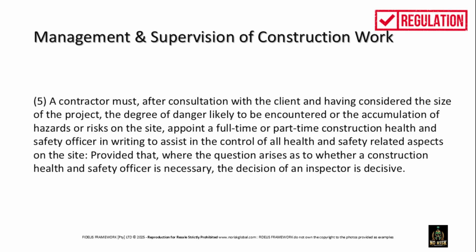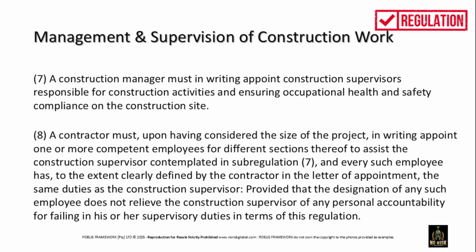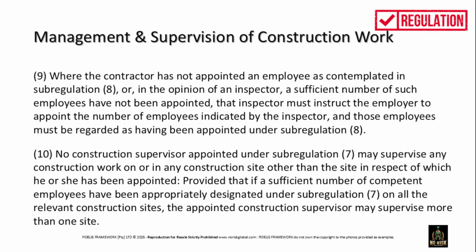Contractors must appoint health and safety officers based on project size and risk, with inspector approval if necessary. Health and safety officers must be registered and competent to assist contractors in managing site safety. Construction managers must appoint supervisors to ensure safety compliance, considering project size and employee competence. Supervisors must manage construction work, ensuring employees are appropriately designated for site safety.